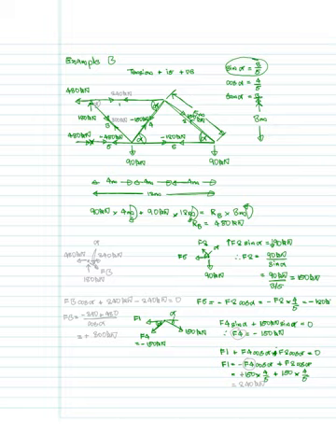So of course, since F4 is negative, the two negatives cancel each other out, so you get 150 times 4 over 5 plus 150 times 4 over 5, and that's going to be equal to 240 kilonewtons. So let's write 240 kilonewtons for F1.